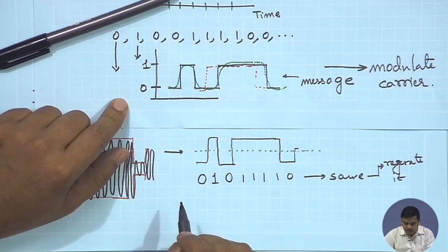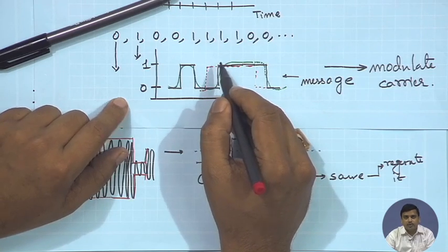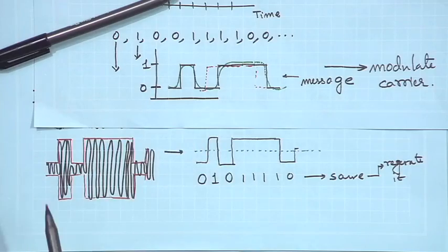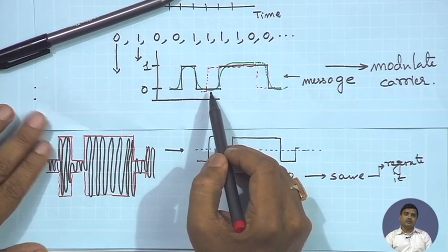In analog communications, this distortion is almost impossible to correct, because you do not know what is going on, you do not know what the message is, because this message is something which is generated at the source. If you knew the message which is to be sent, then you would not send the message. That means, if I know already what will be sent to me, what is the need to send that message? So, at the receiver we do not know the source message a priori. So, this particular mistake will not be captured and it will be used as it is in analog communication.